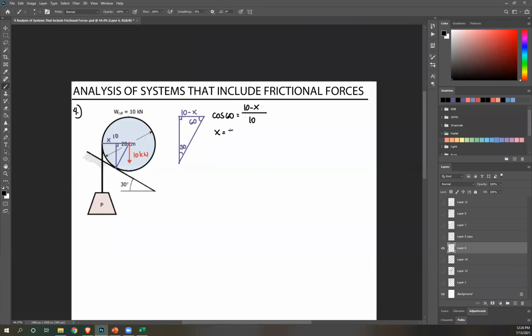Okay, yeah. 5. Okay, now I know the perpendicular distance. I can move on with solving for moment. Okay, so summation of moment. Let's call this point A. Summation of moment at A equals 0, right? Weight is always downward, so downward rotate about A, that's counterclockwise. So negative P, again perpendicular distance is X.